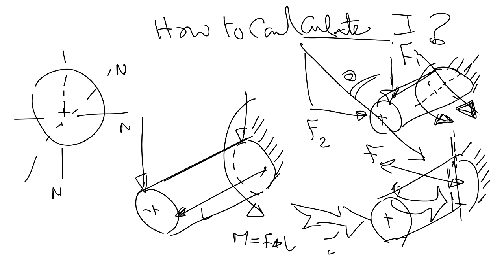Like not real. Not real, yes. If you move your force from a place to another, it should be accompanied with a moment. And this moment is equal to the force times the distance that you moved this force virtually. Okay.